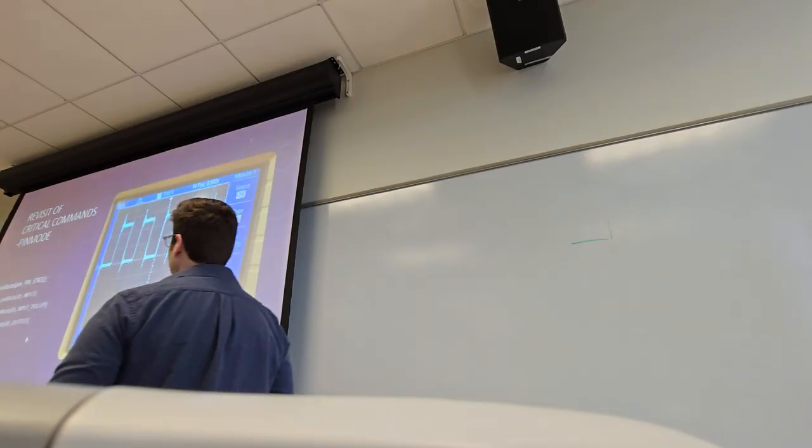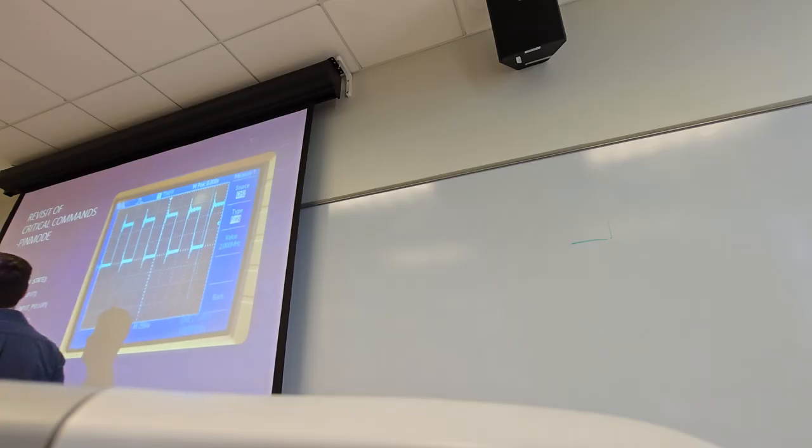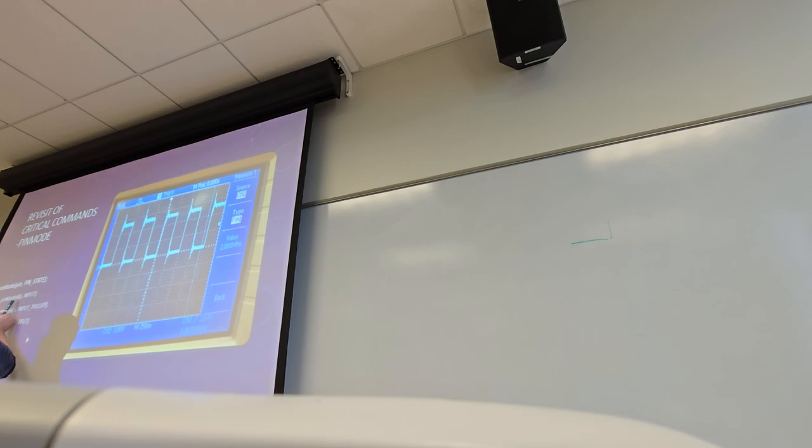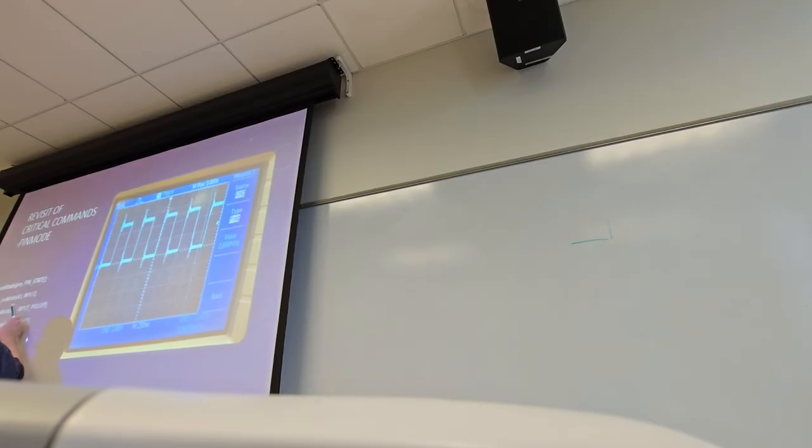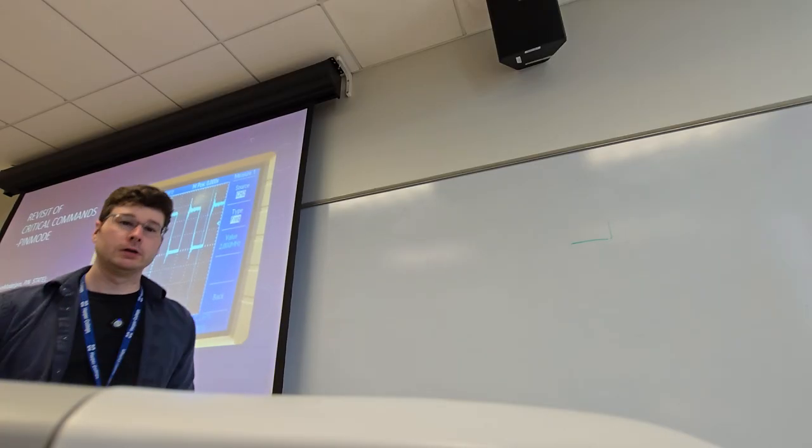Okay, the pinMode function takes two arguments. It takes a pin argument: which pin are we changing? In this case, we're changing the A5 pin, or the analog pin. The analog pin can work with digital too. And we're changing it to a state, a configuration, right? So input, input pull-up, or output. It's three choices.